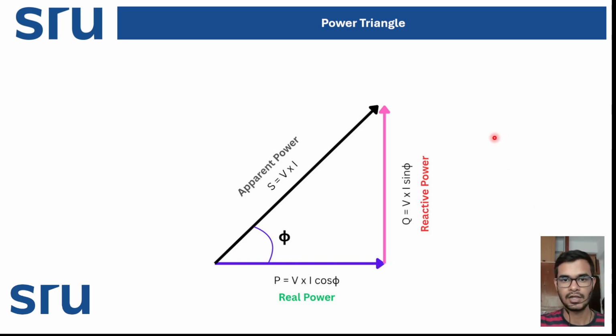Coming to the power triangle, here we have real power, reactive power, and apparent power. Real power depends on three components: voltage, current, and power factor. In the previous lecture and example, I had taken only two inputs, V and I, assuming it is working at unity power factor. But here we will take some phase difference between voltage and current with a pi angle, and we will find real power, reactive power, and apparent power, all three, using a single command.